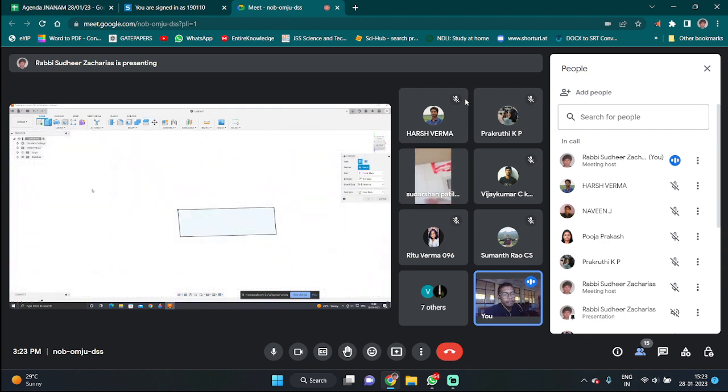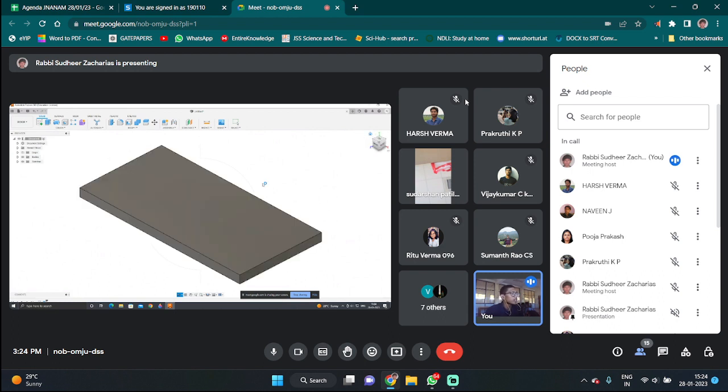So after clicking on that, you can select the previously created plane, and now it will ask you for how much to extrude. So let us say it is 5 millimeters in thickness. Okay. So now we have a rough block, a rough phone like block. And if you want to again reset your vision, you can just go to the top right corner there, and you can see that home icon. So on clicking that, it just resets the view. Okay, fine.